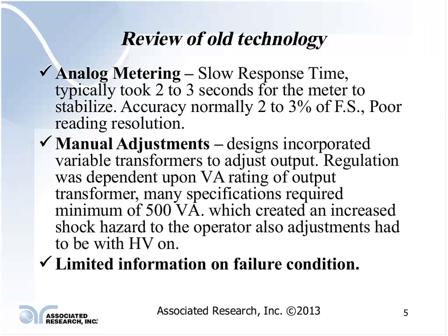In a lot of cases, you're testing a product that draws only a few milliamps of current, and if that's the case, then why do you need something capable of supplying 100 milliamps, if you can use a tester supplying 20 milliamps? It's a lot safer for the operator.